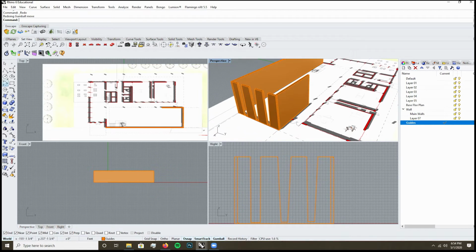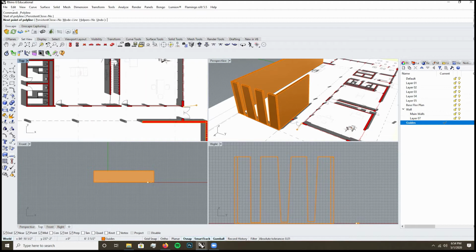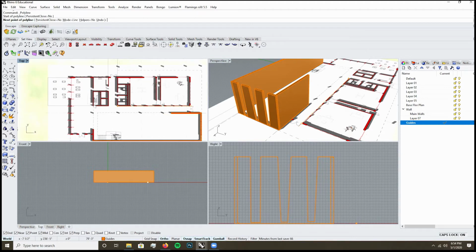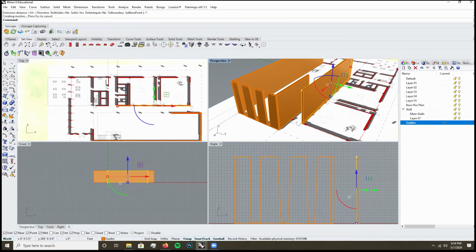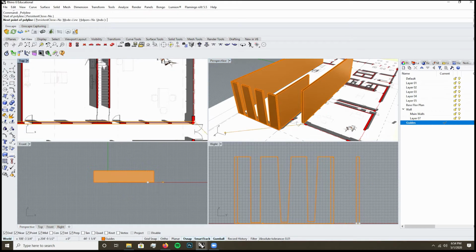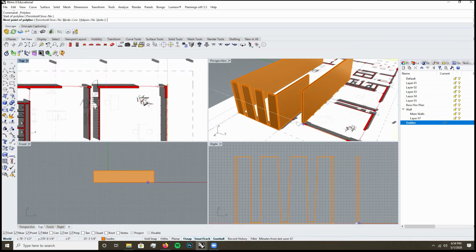wall how I want. Come here, go into plan, make this long wall, extrude, snap to the top, select, do border, record history, extrude. It requires an additional step, and so there might be a lot of circumstances where you foresee that you don't need to do that, and that's fine too. But if you do take the time to make that additional step, it will save you.